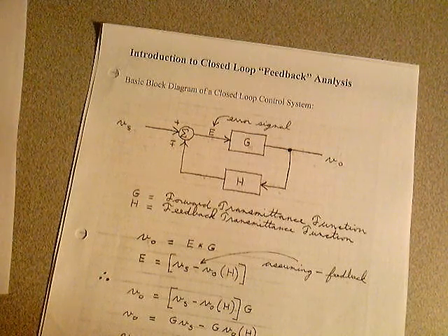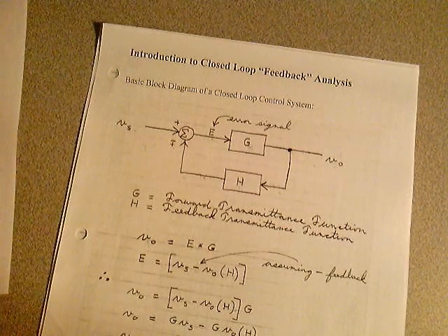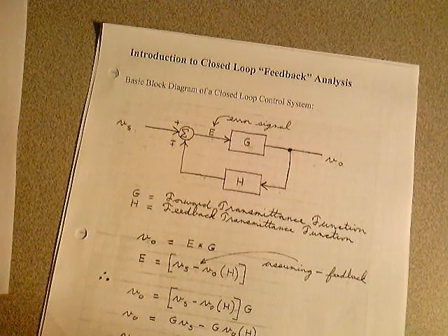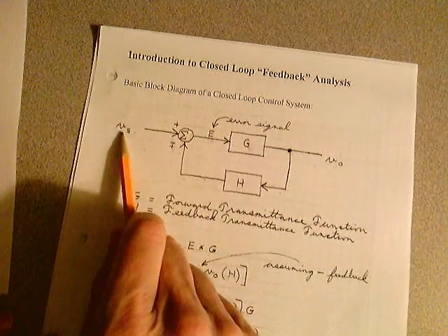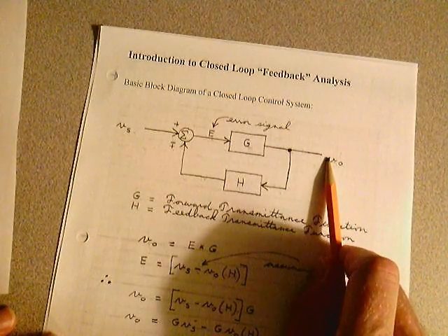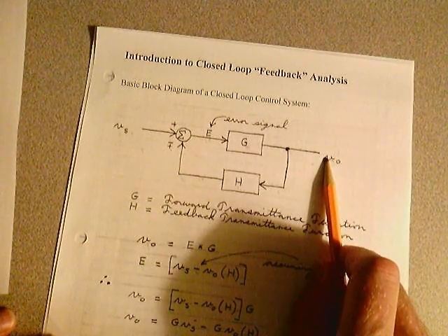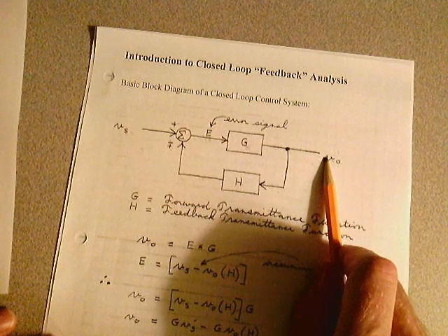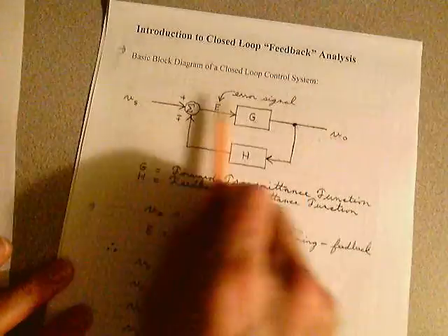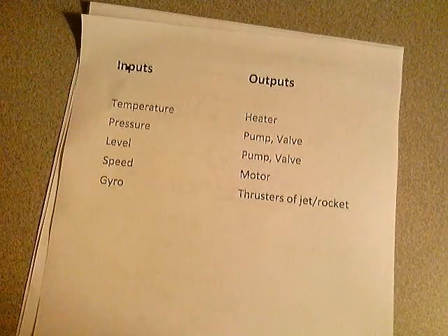As it's gone vertical, if the thruster on the right starts to lose power, that rocket's going to tilt to the right as it goes higher and higher. So you would have a gyro sensing that, and you could go ahead and control the thrusters, that particular thruster. Give it more voltage. Give it more power. So that's how this control system works, controlling those outputs with these inputs.